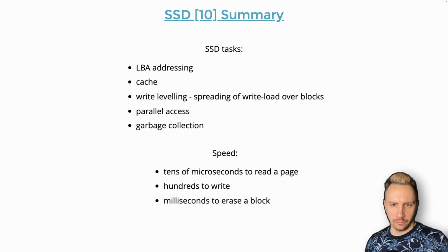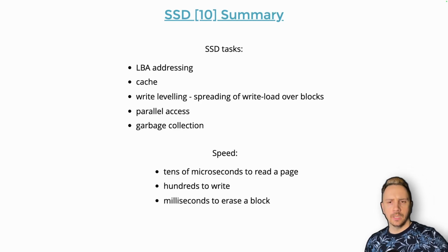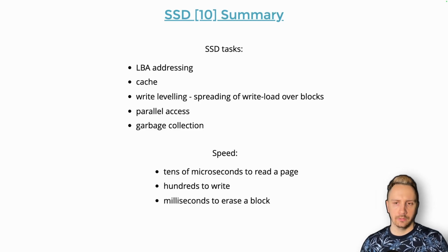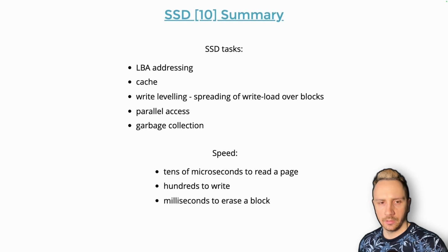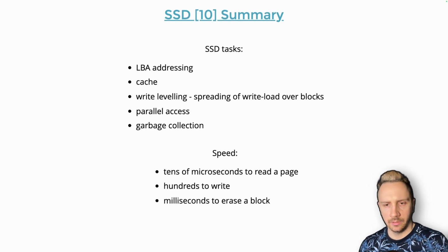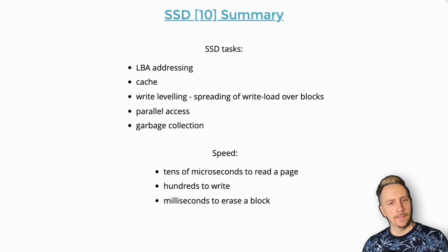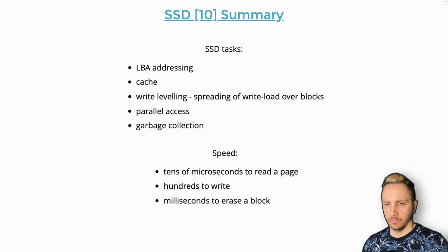As you can see, SSD is a very complicated thing. In terms of logic, the controller here has to perform a lot of tasks. An SSD can basically be called a separate computer. Its controller should be much more complicated than for HDDs, because not only does it have to route your read and write operations to specific memory blocks in the device, it also has to perform garbage collection, block copying, removal of pages, and reset of whole memory blocks. There is a lot of software in the SSD which does a lot of work outside of the kernel, just inside the device.